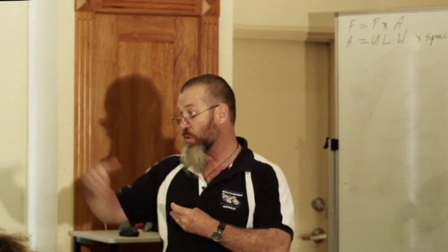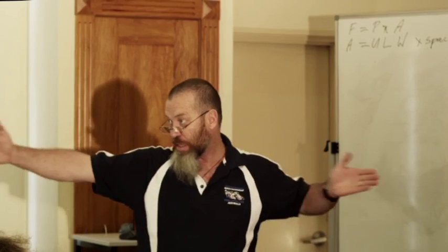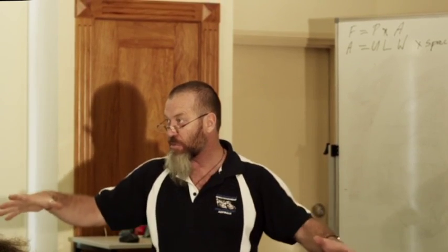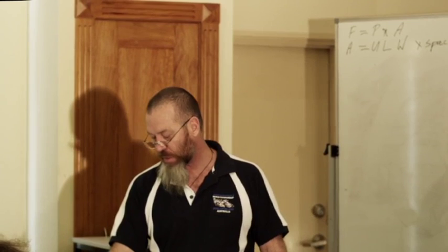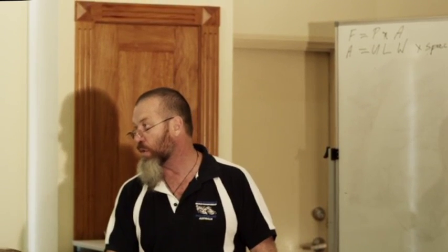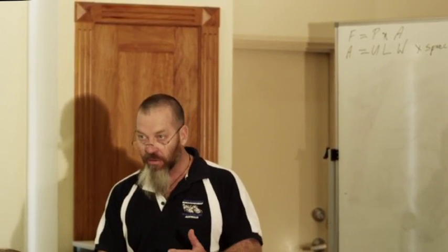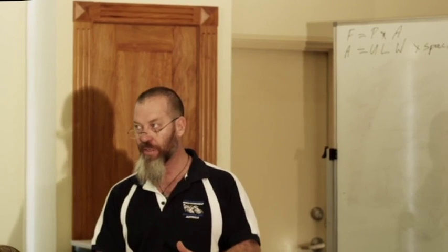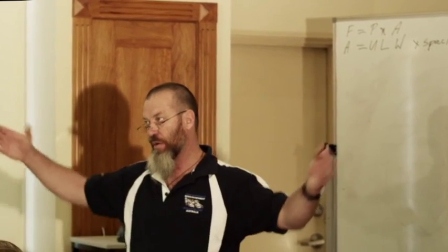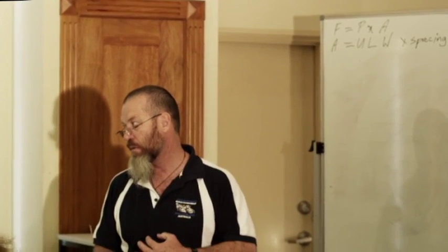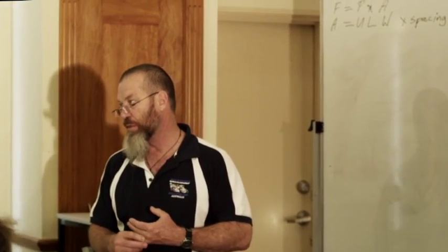So you might put it on every 3rd rafter, so you stretch that spacing out, therefore you've got a larger tributary area. You look at the minimum force there in type A connection, 4.2 kilonewtons. Generally, N2, N3, you'll have one of those connections every 3rd or 4th rafter. That's what you should be doing.